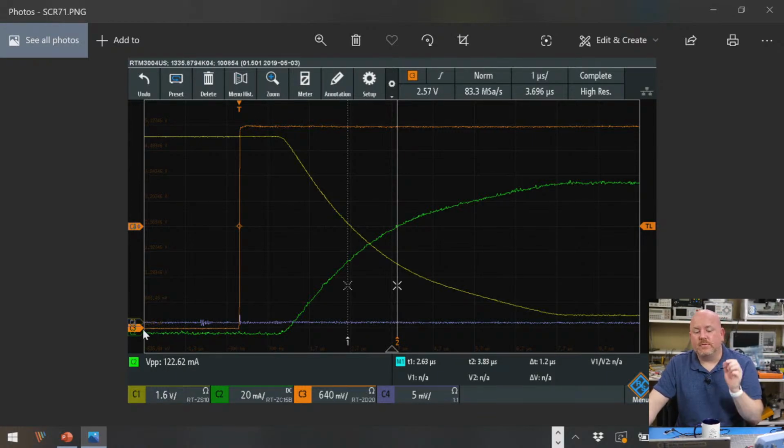So notice how with the 3K resistor, there's two things that really are interesting. Number one is the gate does a really nice change from 0 to 5 volts. Now this is actually relatively slow. It's much slower than what the previous shot showed, but there isn't that whole ripple or plateau effect that we saw.